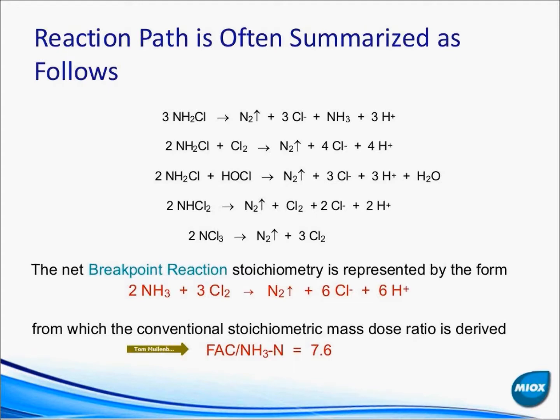and then finally getting to this endpoint. So bleach very commonly, and again in my previous career when I was designing these systems, I would oftentimes recommend folks, you're going to have to plan on about 15 parts per million of chlorine bleach. Where mixed oxidants can fit into this is that we tend to drive the reaction much more closely to stoichiometric. So when we're recommending a design, we'll say you're probably going to want to dose somewhere in the range of 8 to 10 parts per million,